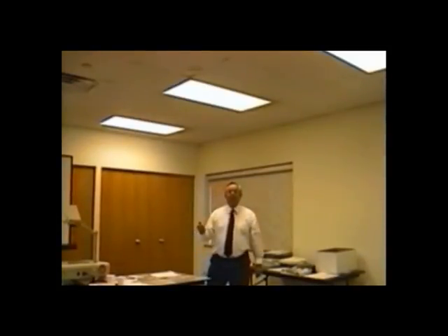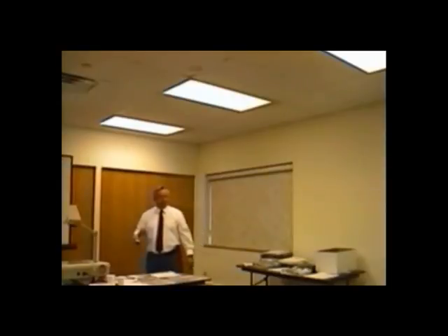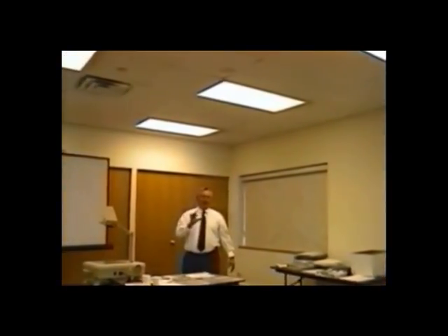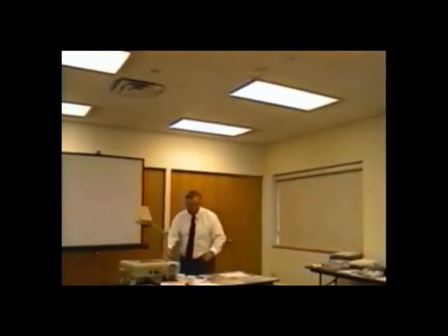When you call for technical assistance, many times we will ask you, did you soft solder the unit in by using 95.5, or did you use high temperature brazing? The only acceptable method of installation is high temperature brazing. Silver brazing with Sulfos, or high percentage silver with silver solder. No 95.5. Low temperature soldering is for plumbing, low pressure. Brazing is what we use in refrigeration.